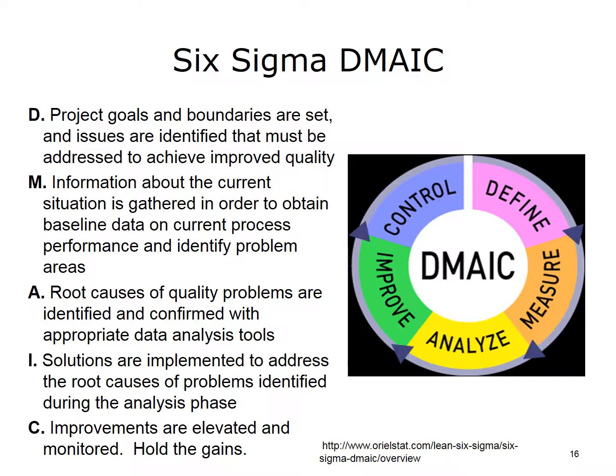Six Sigma was developed by Hewlett-Packard, Motorola, and GE, and comes directly from quality thinking in the 1930s. It combines established methods such as statistical process control, design of experiments, and failure mode and effects analysis (FMEA) in an overall framework with the primary aim of reducing variation in the process. Six Sigma aims to reduce variation through 5 clearly defined steps: define, measure, analyze, improve, and control.